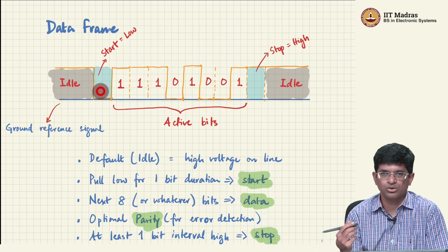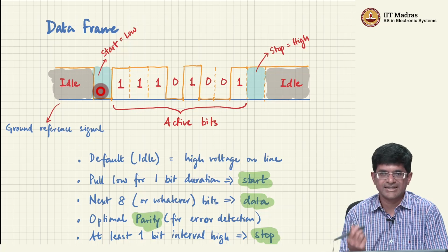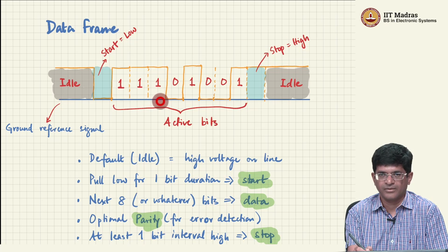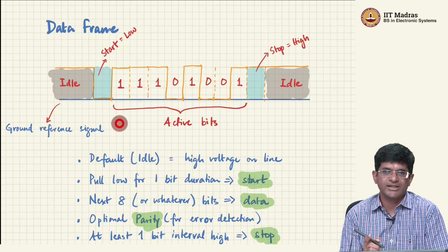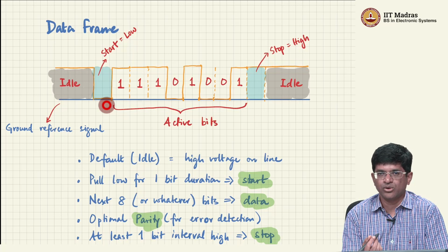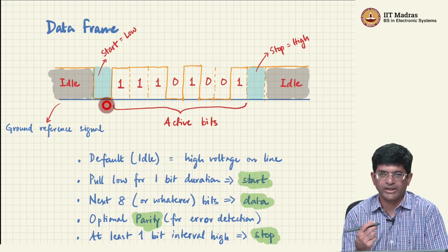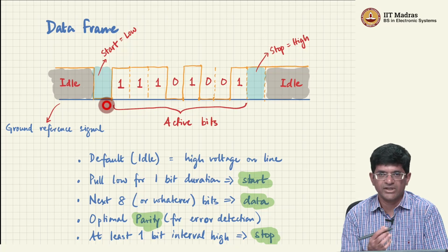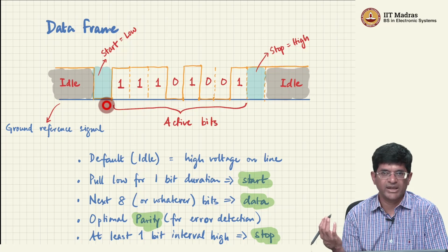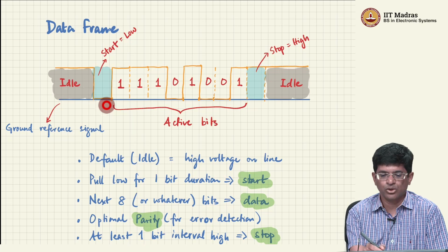Immediately CPU 2 has some circuitry internally which detects the start bit and then says, okay, now I need to start looking at the data coming in here. CPU 2 also needs to know the bit duration, that is how long each bit is supposed to be. Now, how do I get this information to CPU 2? I have to pre-program it. I have to tell CPU 1 and CPU 2 the speed at which they are going to communicate. As long as they both agree on it ahead of time by some other means, CPU 2 knows the duration of one bit.